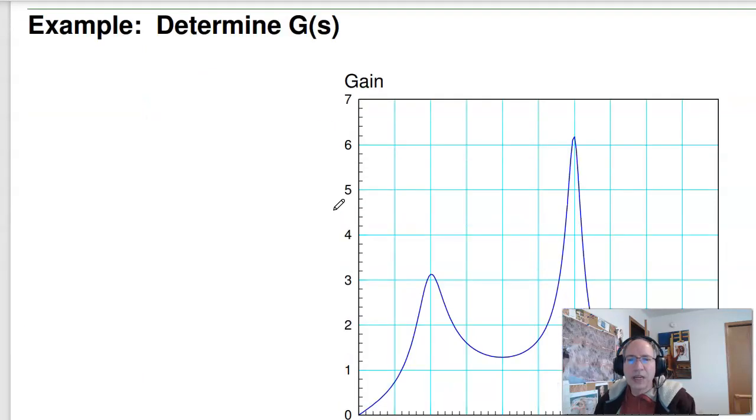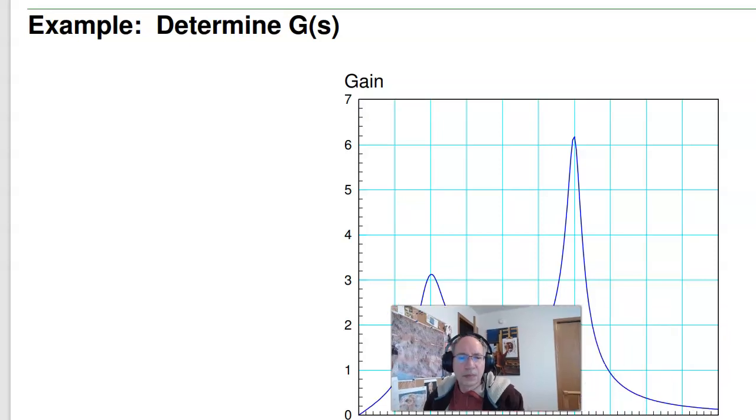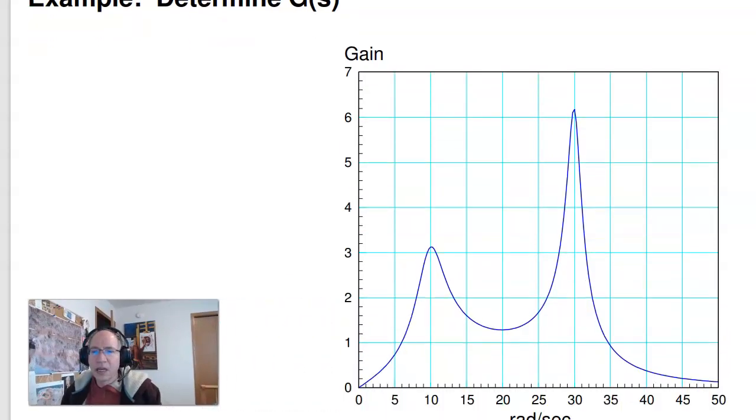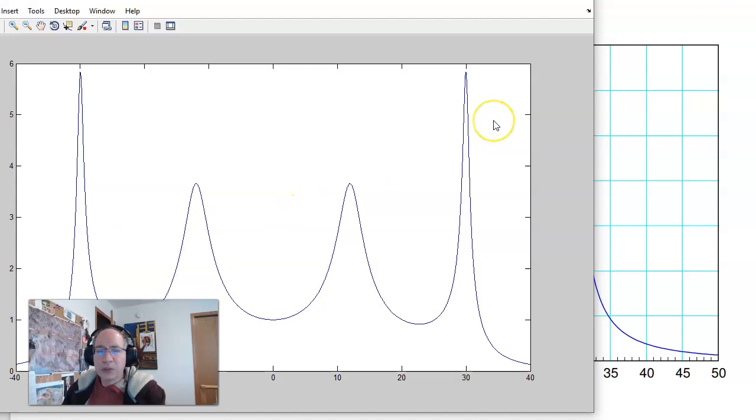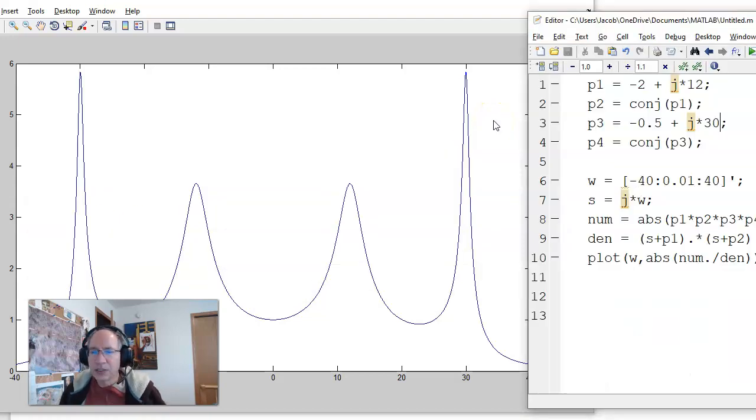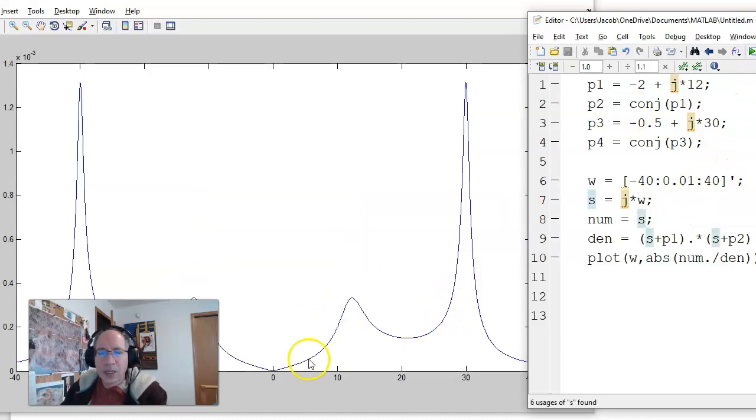So with that, if you had a gain versus frequency like this, which is kind of like one of the handouts, I can sit there and calculate the transfer function. Oh, actually, let's back up for one thing. That's for poles. If I do zeros, zeros force the gain to 0 at a certain point. So if I said the numerator is just S, and then plot it, now suddenly the gain at S equals 0 is 0.